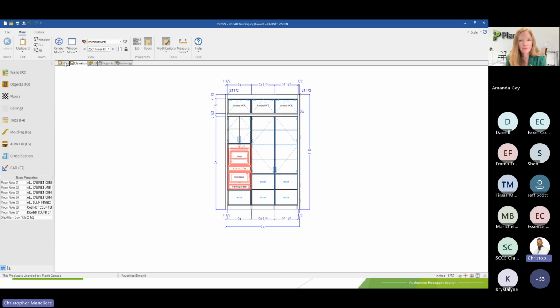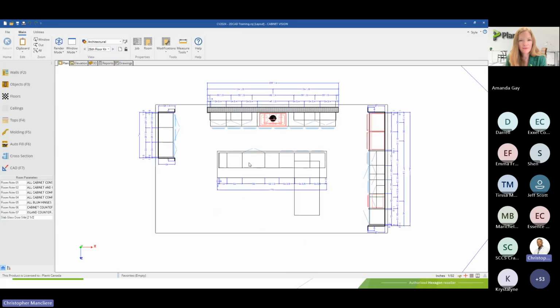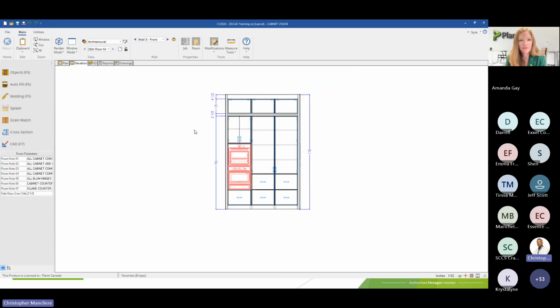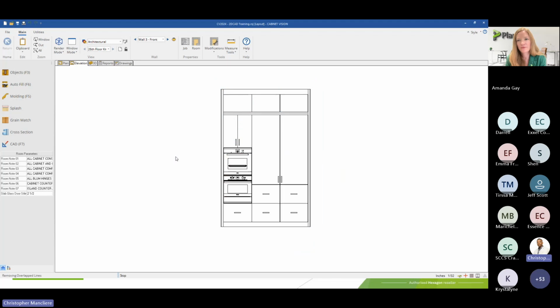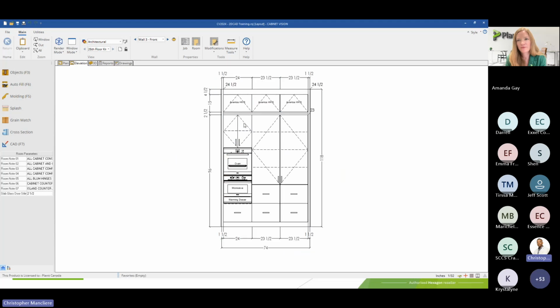And as I said, this is only for the elevation view. So this is specific to the elevation view. If I do a quick test of sending this to the drawings, let's say I right click outside my wall, select the option to drawing, I will already have a preview of my drawing being sent with now the indication of the door opening as well. So that's a feature that I like to turn on.